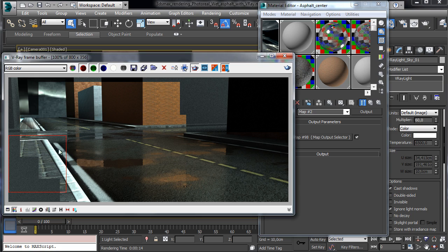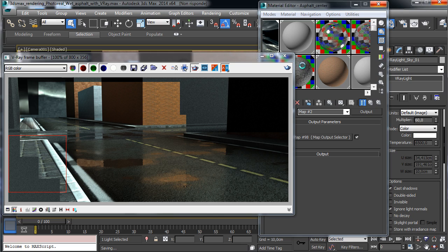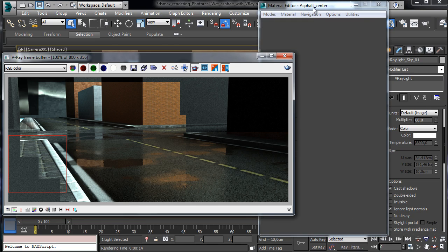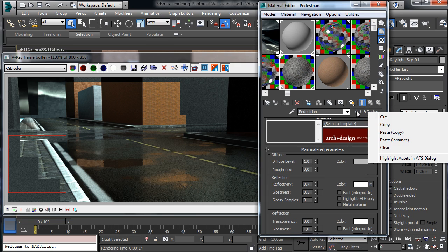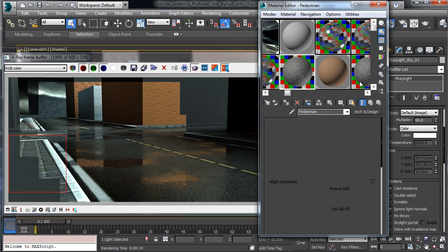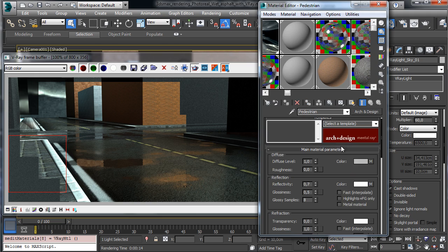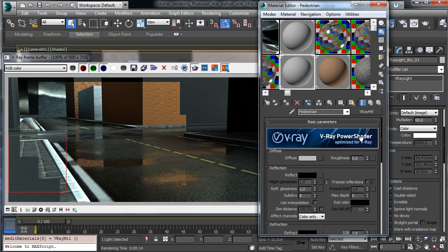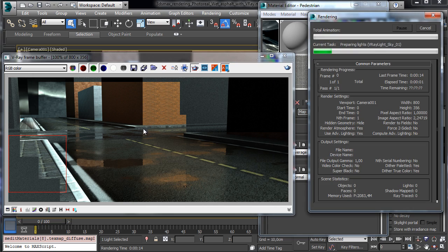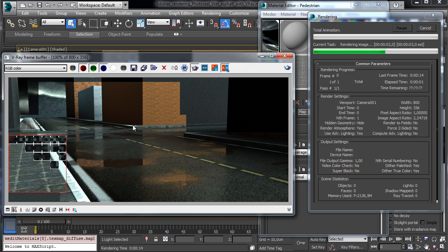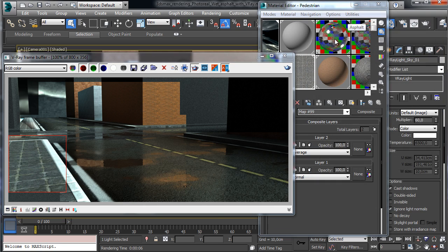And then let's go to play with this material. And we are talking about the pedestrian. Let's make a copy. And we can do there a VRay material. And let's start to have the same process. So we need the diffuse map, and we have this kind of map. We can render just with the diffuse. You see, that's the map we have.